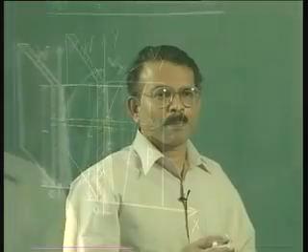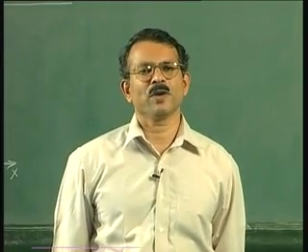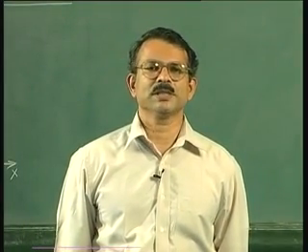Now what are the equations that will be used? Recall what we said in the procedure for device analysis lectures, that any device can be analyzed using the 5 basic equations, that is the 2 transport equations for electrons and holes, the 2 continuity equations again for electrons and holes, and the Gauss's law. We have already shown how using this we can derive the equation for p-n junction and for bipolar transistor, which is based on p-n junction.